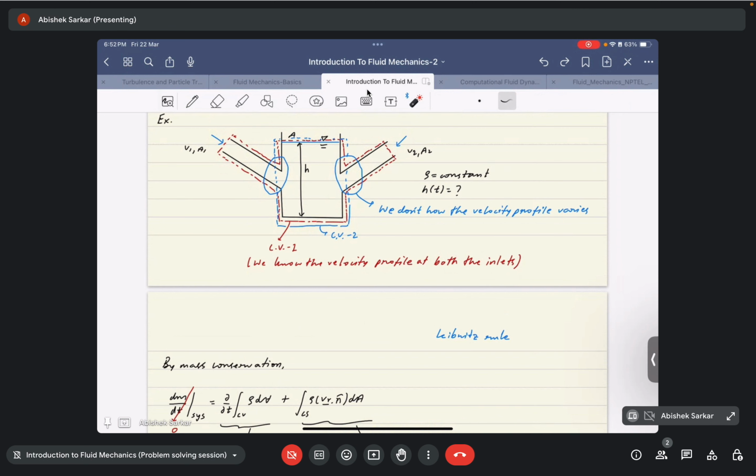Now the velocity profile in this part can also be approximated. If we assume it to be cylindrical, and we know the velocity profile at the inlet is uniform, again we can apply conservation of mass to find the approximate velocity profile in this region. I'm not saying it's not possible to find the solution. It's always possible, but it's a very tedious and time consuming work, and you need to apply conservation of energy to take into account the height difference in these two regions.